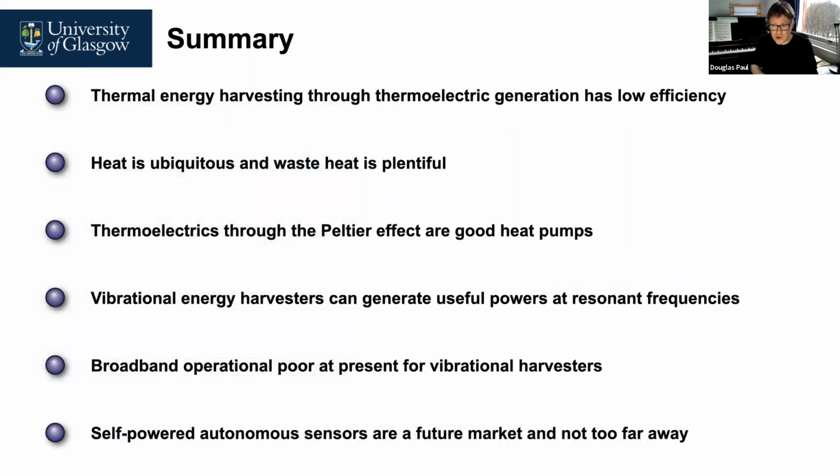Well, that's the formal teaching for today over. I've gone through thermal energy harvesting using thermoelectric generation and demonstrated it typically has very low efficiency. Heat is ubiquitous and waste heat is plentiful. So the big advantage of those thermoelectric systems is that you're getting the fuel or the energy for free, if you like. The other big advantage we spoke about is they really are fit and forget solutions that you can put in and not have to worry about them, certainly for many decades.